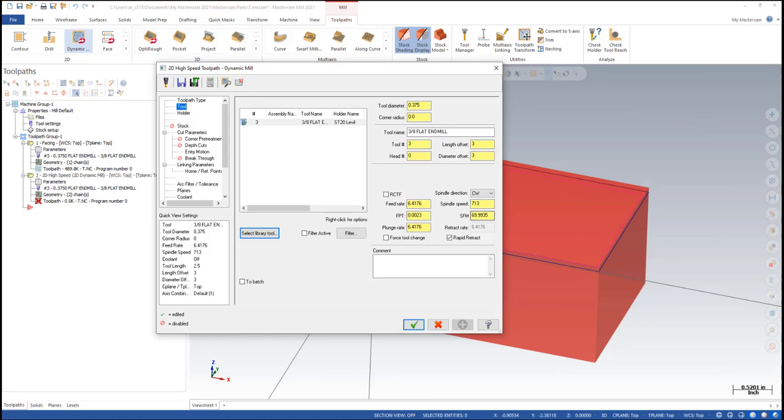However, our speeds and feeds have gone back to their default settings, so we can just populate those again, 500 and 32. Again, we are not plunging into materials, so we can go kind of quick on that, save a little bit of time. And we will engage radial chip thinning.